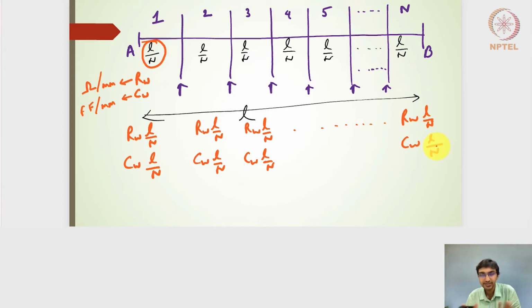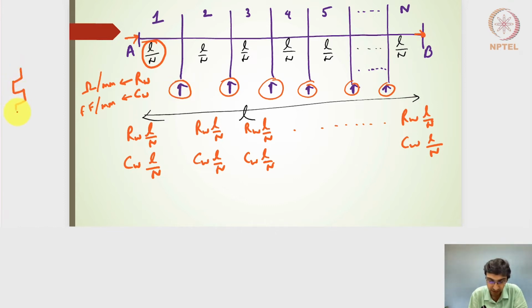Right, so the first thing is the repeaters have been added here at each of the n-1 segments, so that my overall signal strength, while the signal starts from A and reaches B, will be good, not attenuated anymore. Remember that this particular repeater is nothing but an inverter. So if I consider the inverter here, at each of the repeater points, n-1 points, I will have a VDD rail or a ground rail.